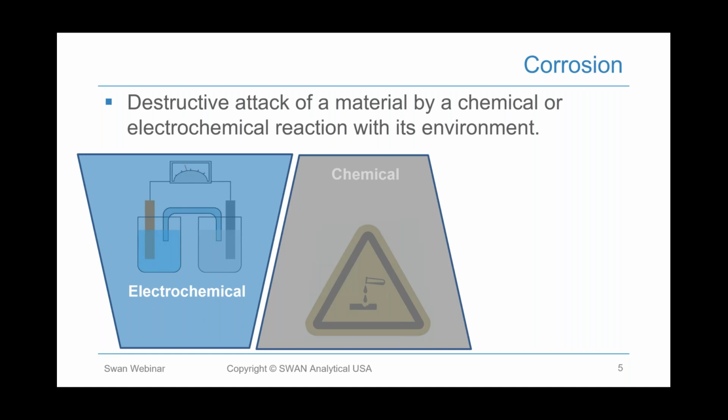So this is a diagram on a little bit about what the electrochemical process is. So we've got electrons flowing from one side on the metal pipe surface to another. And you can see on the right here is our anode. So if you can picture a probe that you might have in your lab or in a process, you can know where the anode is on that. So the anode's where the oxidation occurs and the electrons are lost. And then the cathode is where the reduction occurs, where the electrons are accepted. So this is actually happening at multiple places in the pipe.